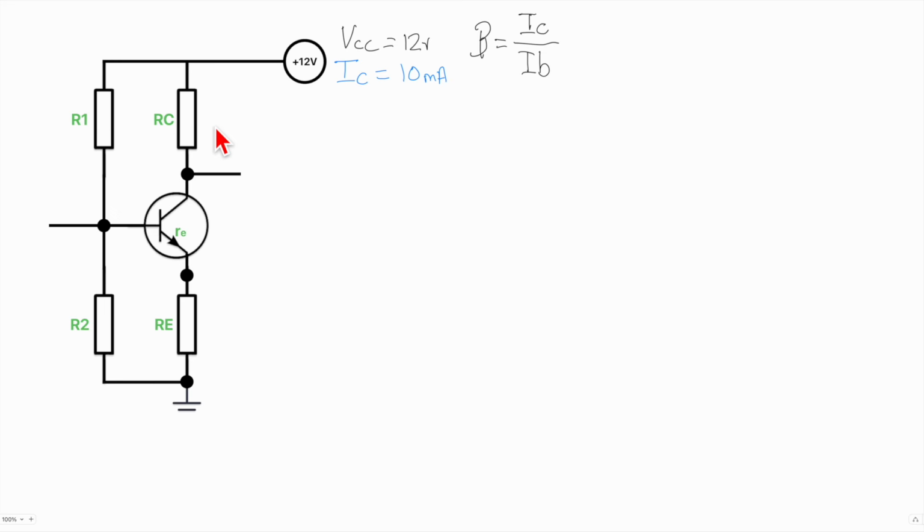And that's because if you think about the base current coming in, the base current is flowing from the base to the emitter. So let's say the beta was 100, for instance. So we've got 100 times more current here than we have here. So, you know, that's easy. But here, we'll actually have beta plus 1, 101 times more current.